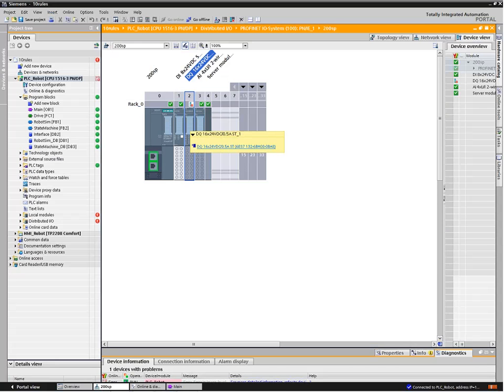Now we can actually see that when we're doing our diagnostics, if we can figure out what the fault was, then we can repeat it. And now we see that that's the fault. So maybe, for example, I doubt somebody's pulling the module out in the middle of the night. Could happen. Maybe it's just loose in its socket. Who knows? But in this case, the diagnostic tools for intermittent faults are really invaluable.